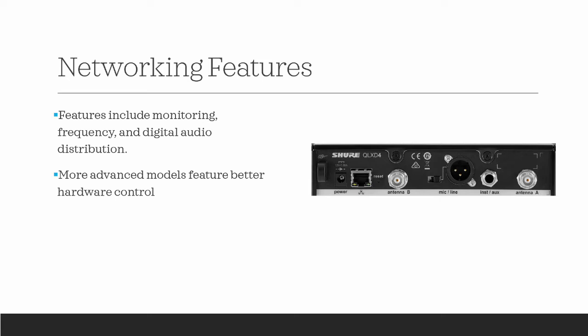that's very common. The other thing that's important to note about them is because they broadcast in the 2.4 gig band, you're able to use them worldwide without any need for special licensing. So if you're going to be doing an international tour or something along those lines, you don't have to worry about getting into a new country and having the frequency space that your wireless system takes up be illegal in that setting. That happens from time to time. It's something that is important to note. So that's definitely a benefit of these 2.4 gig systems.